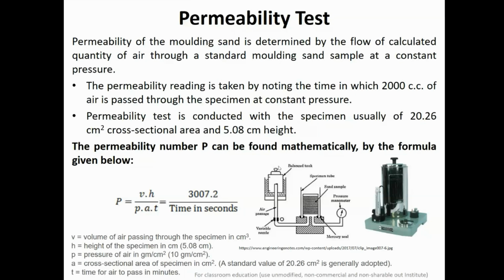When you keep this balance tank at this position, it will try to get submerged due to its own weight, and with the pressure the air will go inside the air passage and try to escape out through the sand sample.